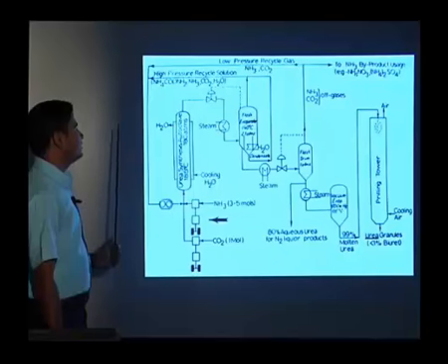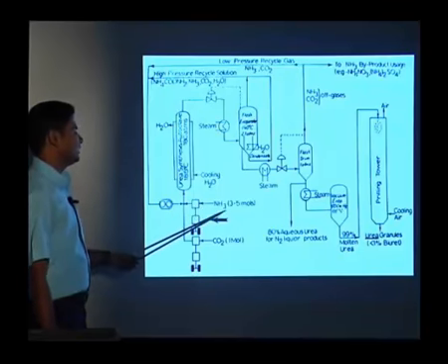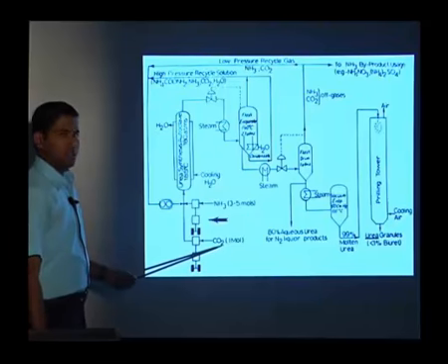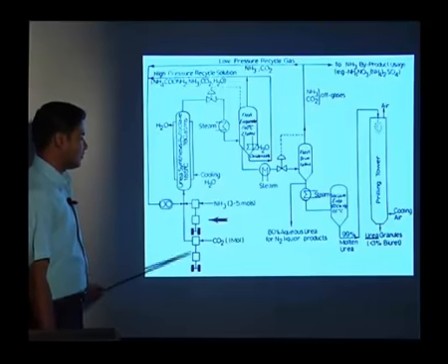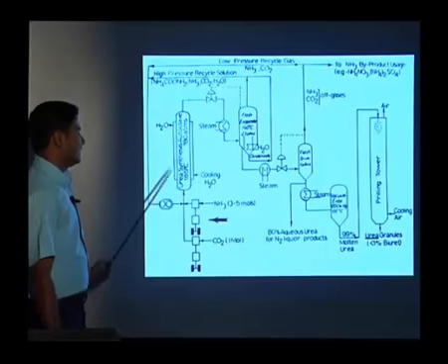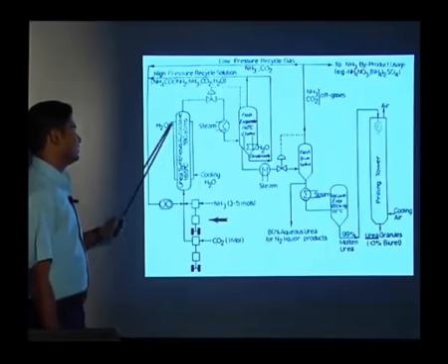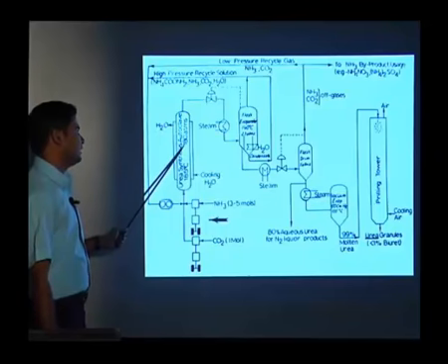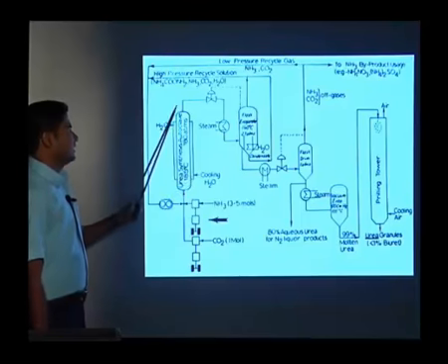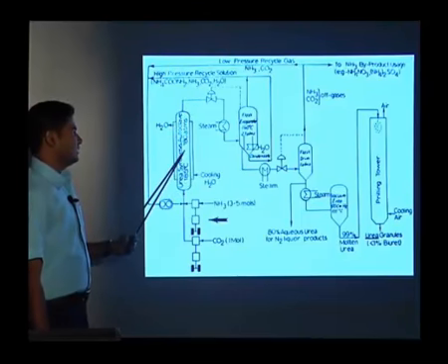So we have the ammonia and the carbon dioxide. Here we can see ammonia 3 to 5 moles and carbon dioxide 1 mole. They are compressed separately, then fed to the reactor. So the urea synthesis autoclave is kept at 180 atmospheres and it is water cooled, as mentioned. Then the residence time will be 1.5 to 2 hours.